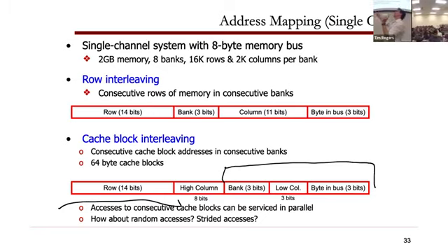So that means I pay a higher initial cost because I have to RAS my first cache block. And it's sort of like I end up getting 8 open rows instead of just 1 open row. In the aggregate, that allows me to cover the latencies better. Does that make sense? I think that's what you mean, right? It's like, we're on the same row anyway, so why do I care? But now you actually have 8 open useful rows, and you can use that to effectively fill the bandwidth of the bus.